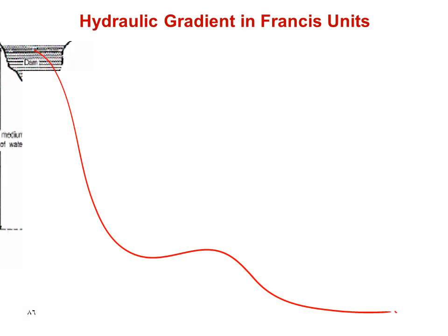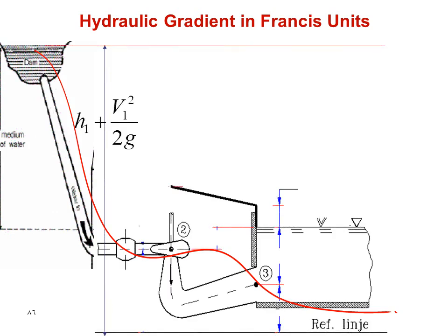This looks like the one in the High Dam, and the flow here is mostly mixed flow, a mix between radial and axial flow. We have here a sketch for the flow through the penstock and through the turbine and then through the guide vanes. And we have here the head upstream the dam and downstream the dam, the head difference, we call it overall head H.